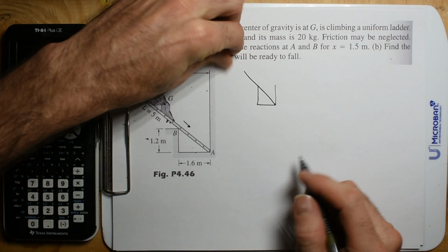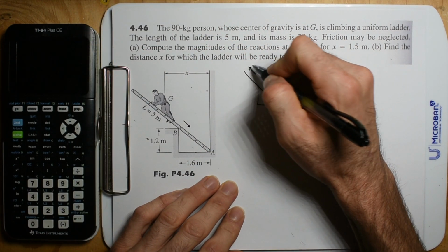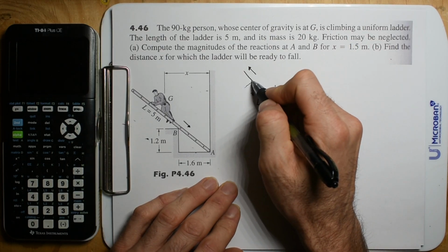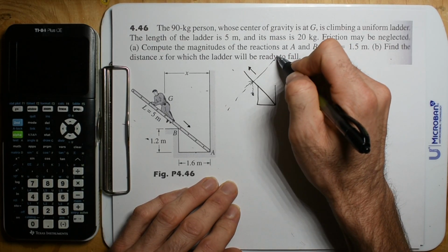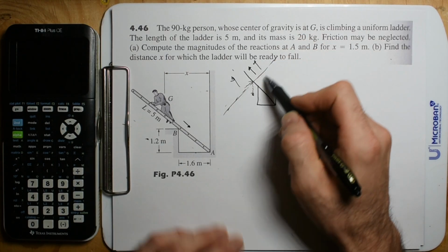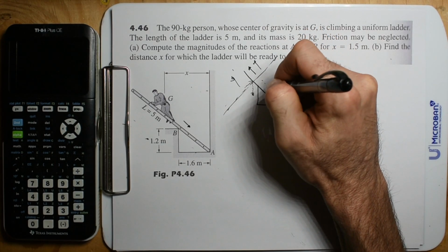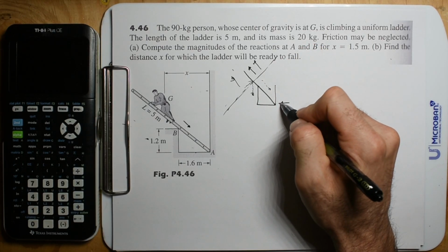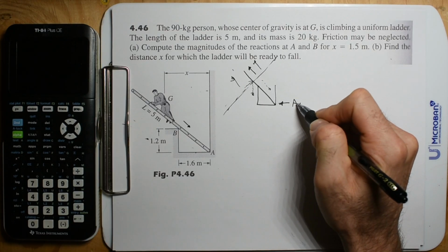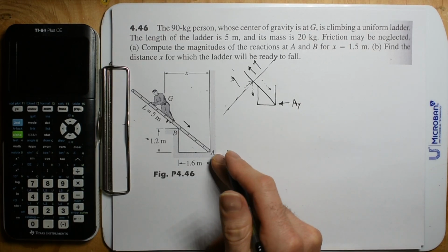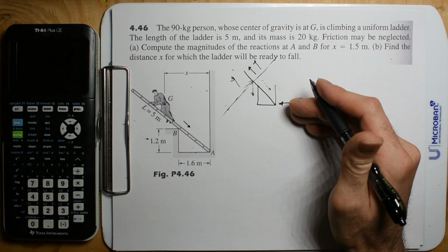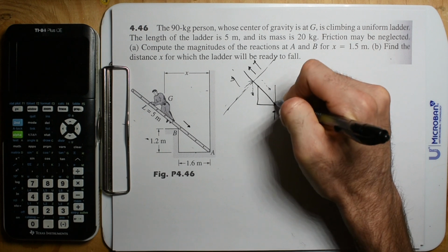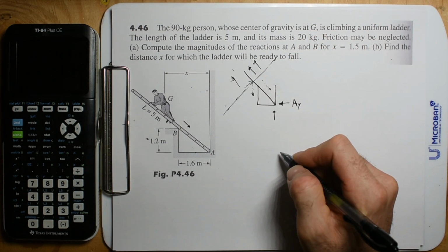If you pull out on the steel rod, that's one thing, but you would have to have a force in that direction. And because the component of the weight is downward, the component of the weight is never on this side. It's never going in that direction. So the weight is always driving this thing back down into the cup, and therefore you generate this force against the wall. And even though it's a frictionless surface, this force against the wall still prevents the rod from lifting up out of the cup.